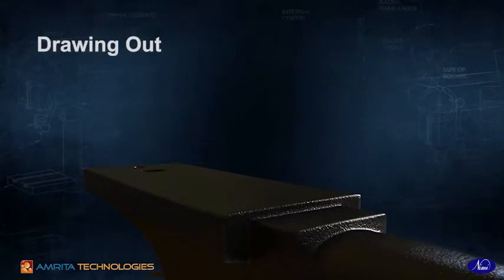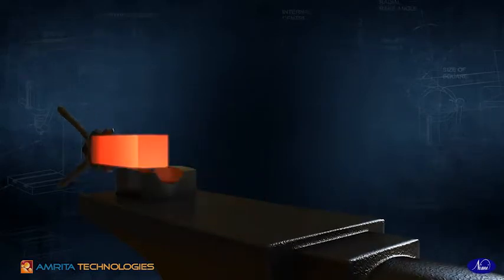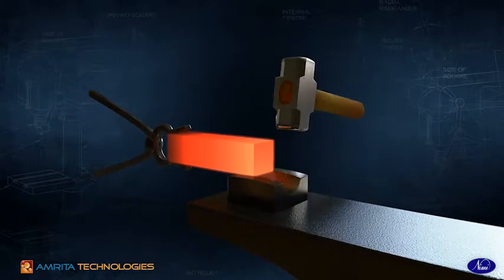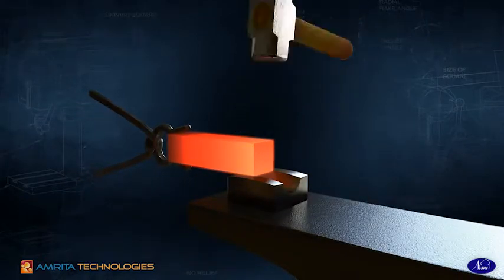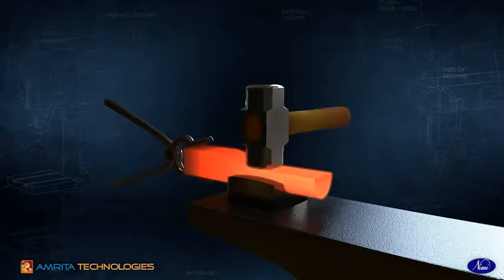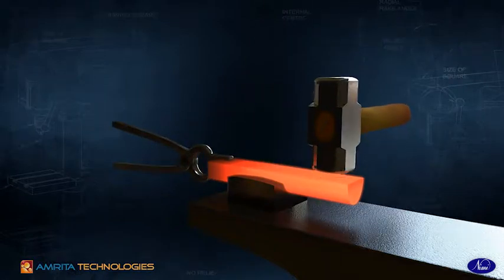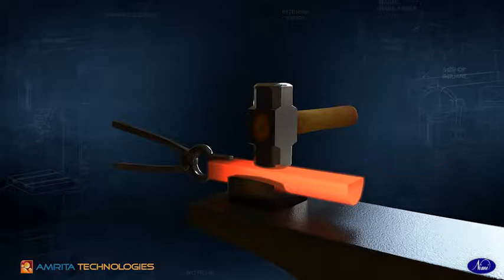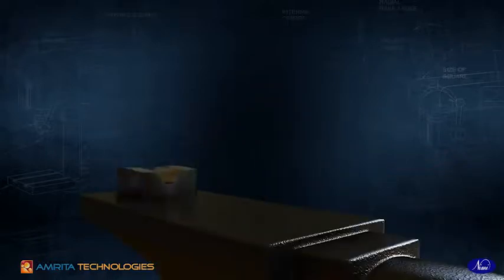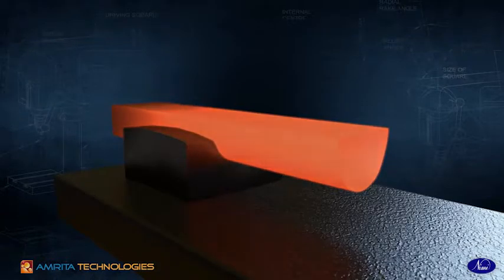Let's now review in some detail the common operations used in forging. Drawing out. Drawing out is a forging operation by which the cross-section of a piece of stock is reduced and the length of the piece is increased. A fuller and a sledgehammer are used for drawing out. It is done on the face of an anvil. The steps involved in drawing out are setting the stock, necking, fullering, and finishing.